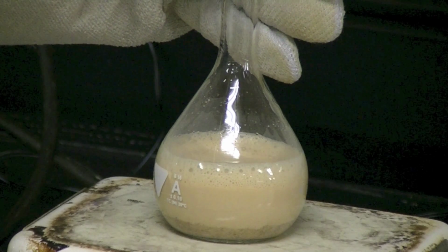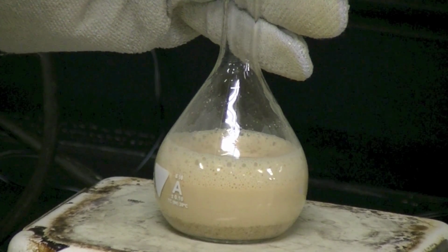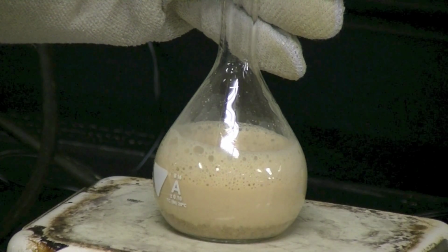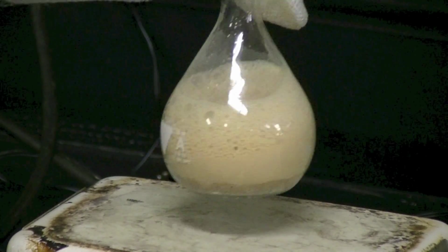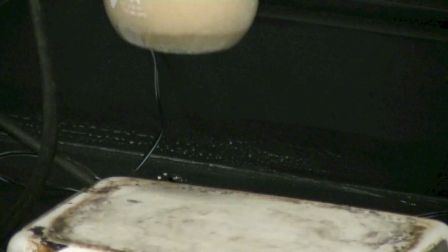Agitate the slurry and keep particles off the inner main body of the pycnometer. We agitate the slurry to keep it consistent and apply the same amount of heat to all particles. Do not allow the slurry to dry within the pycnometer.